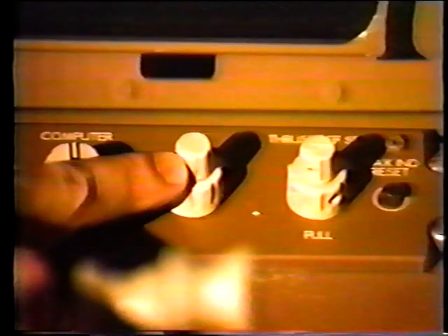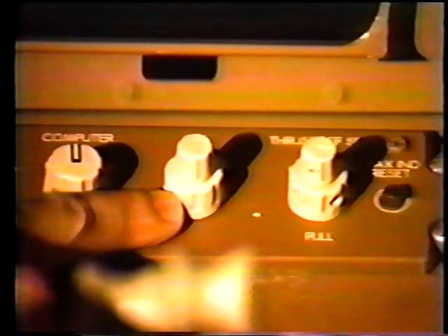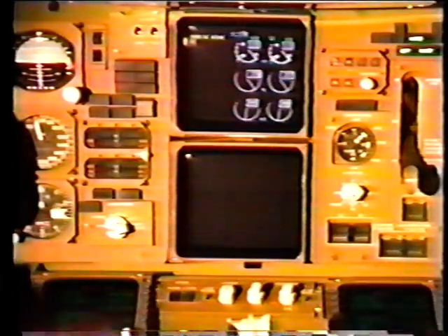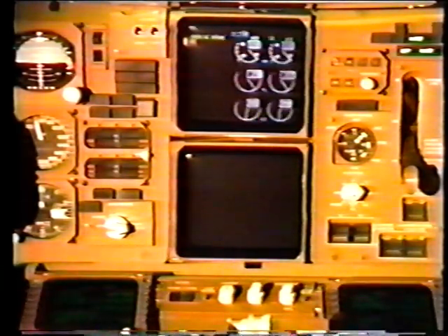The inner and outer knobs control brightness of the upper and lower CRTs respectively. The test reference set knob manually sets the selected engine's EPR reference bug. The maximum indicator reset switch resets the engine exceedance over limit readouts on the CRTs. Exceedance information remains in ICAS memory. Pressing the engine switch removes the display on the lower CRT.